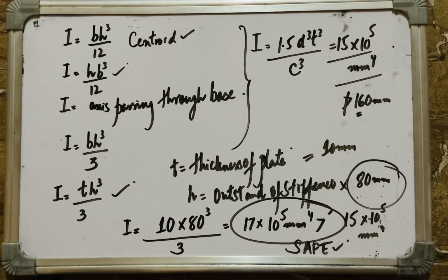If it's greater than 250, then additional horizontal stiffeners are provided. And if our d by t ratio is greater than 400, then our section has to be redesigned completely ab initio. Since our d by t ratio was greater than 90, we have to provide vertical stiffeners, and the vertical stiffeners prevent web buckling under shear stress, especially in areas with high shear forces or concentrated loads.